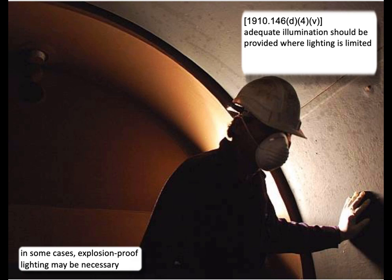You also have to provide adequate illumination inside of a confined space and ensure that that illumination is intrinsically safe, so that just in case there is a flammable atmosphere, your lights don't cause some kind of spark, and that's when you can actually have the vapors ignite, which is much easier than you would think. Enough static electricity can be generated just through the transferring of a flammable liquid to cause a spark that can cause the vapors to ignite.